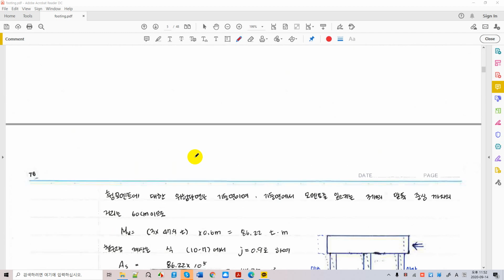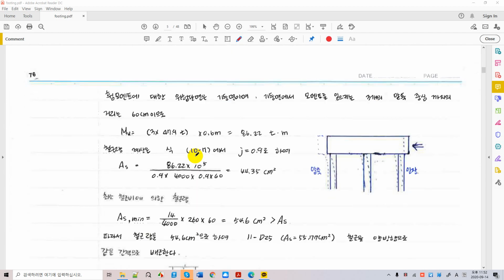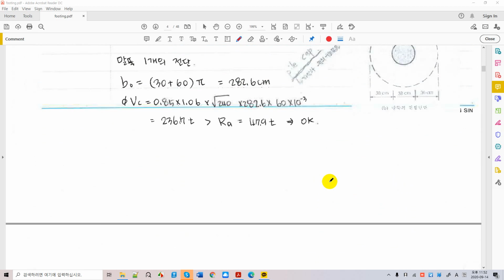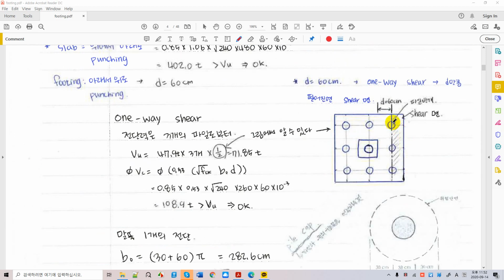All right. And the last item that we need to calculate is the flexural resistance and lever arms to resist the bending moment provided by each pile force. Okay, so if you see the piles, these three piles are going to create a bending moment at this part of the pile cap, right? So the acting face is the face of the column, as you know.